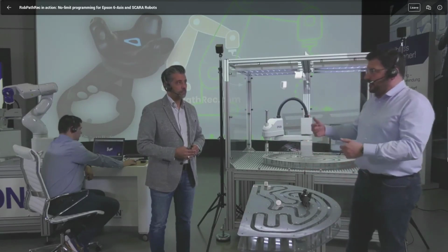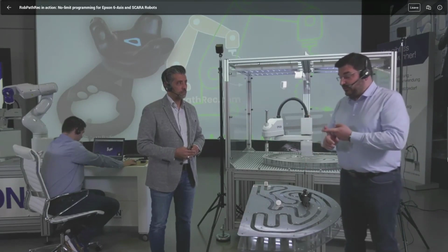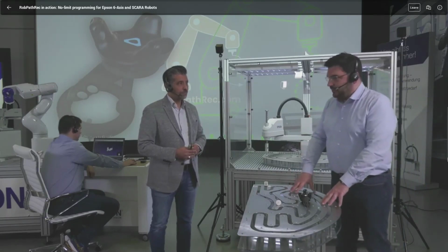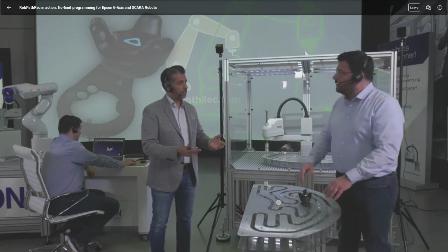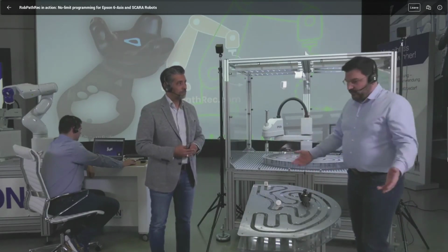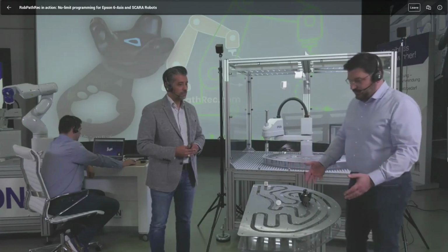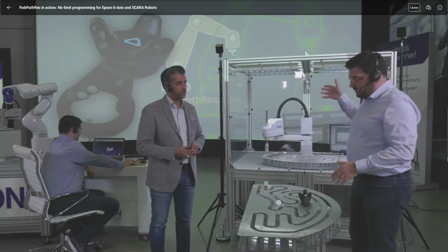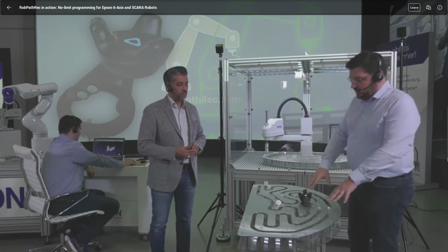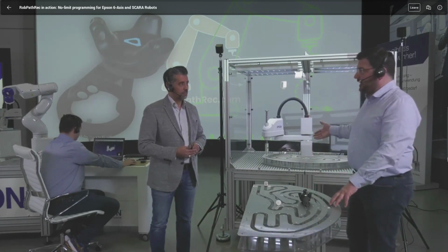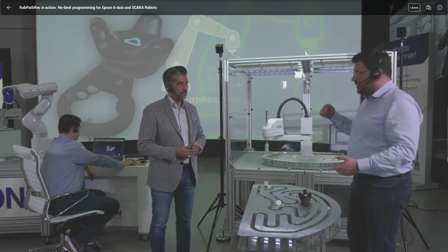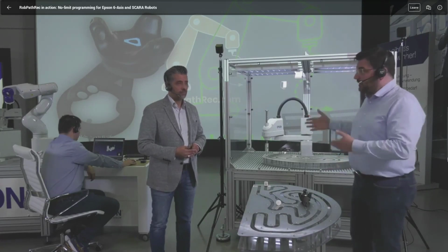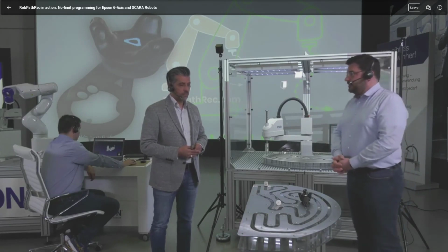You do not need any CAD files for offline programming, but you can really generate the CAD file from the real part, which is created one time uniquely for this purpose, and then you can copy it without any additional effort to the robots, while the robot is really doing the productive work. Once you are ready with the programming, you have to interrupt it one time. It takes approximately half an hour. Then you can check out the finest details to see if it's okay, and then you can continue with your production. Great. So let's look at what Balázs is doing.